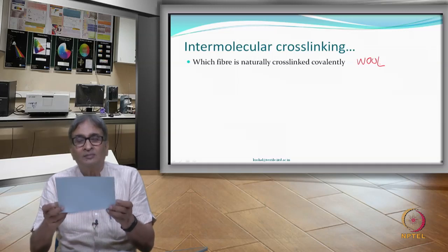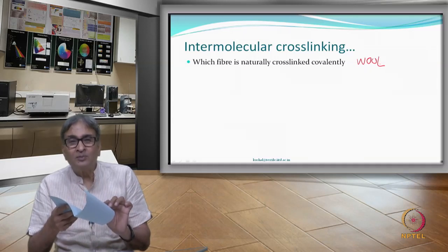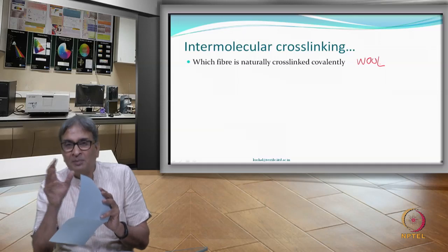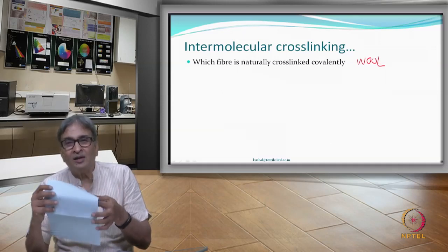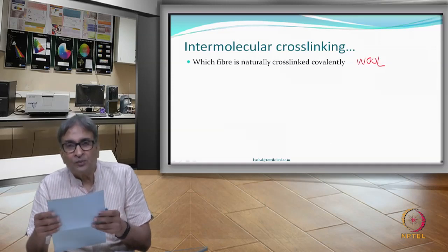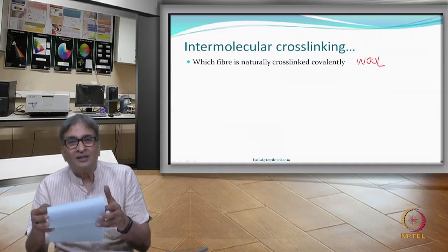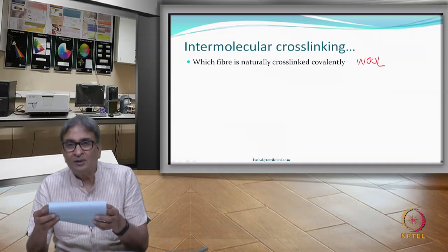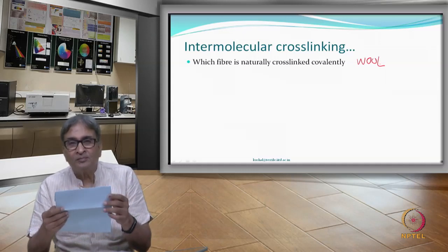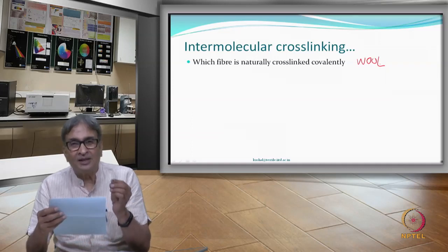Why is it recovering? It is recovering because when we bend, some stresses are imparted, and strain energy, because expansion and compression happens, is being stored. If the strain energy is being stored, then obviously by opening it, it releases the strain energy. We bend again, and there is strain energy stored in this whole process. Here the molecules are getting to change their positions which they do not like, and so when you release the stress they come back. But when you do this, they are not able to recover, because at that point it is such a sharp creasing.